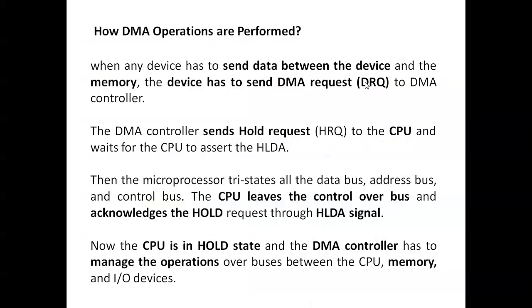Next, how DMA operations are performed. If peripheral devices want to send data between the devices, first of all the DMA request DRQ is sent to the DMA controller. Any device that wants data first asks through DRQ, the DMA request.